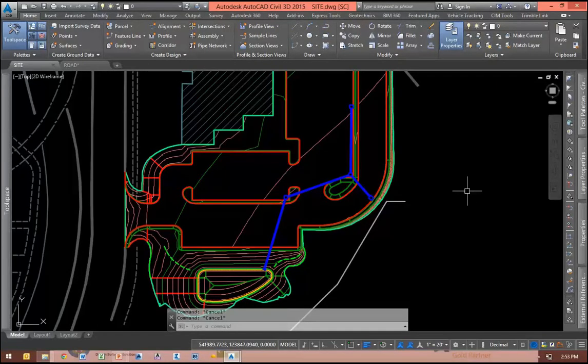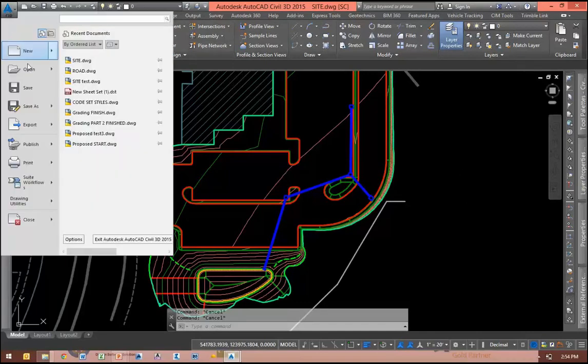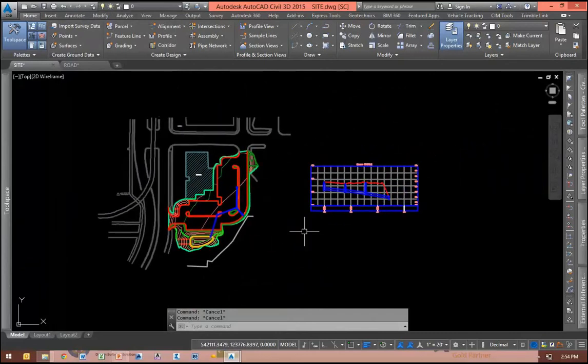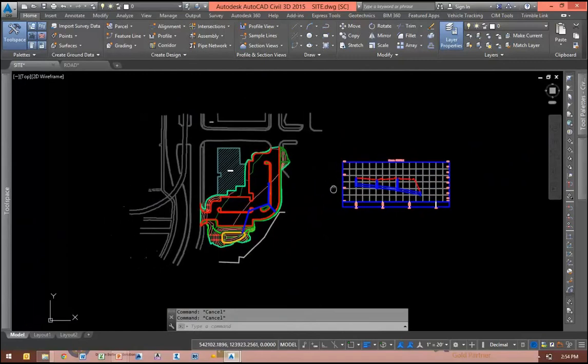I'm going to jump into Civil 3D and show a few routines on this here and a number of different options. We don't exactly have just one workflow to show you here, but rather a few different options. Some of the simplest stuff is to simply take a DWG and export to a DXF. I know a lot of people prefer that because it's really simple. You pretty much hit the Export DXF button. There's some drawbacks to it. You get one file type, it just kind of all dumps into the data collector. And what exports is a little limiting.